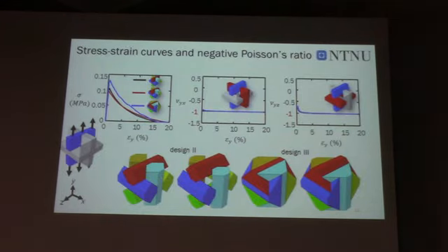And then if we understand the two cases from the analytical models, from the numerical models, from the experimental results, then we have the confidence to move further regarding the families. So here are my families, design 1, design 2, and design 3. In the negative Poisson's ratio cases, what you can see here, the stress-strain curves and the Poisson's ratio diagrams, they have almost the similar trend, right?